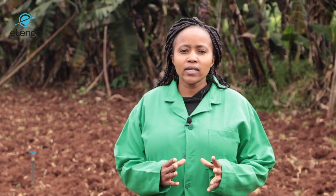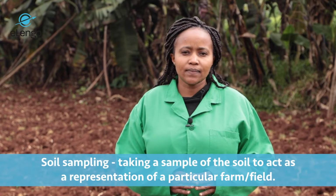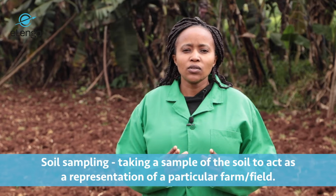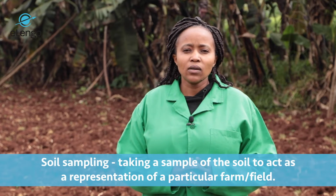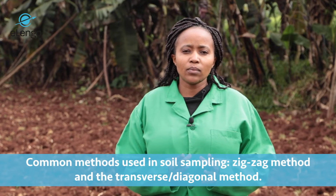In this section, we are going to talk about soil testing and specifically soil sampling. What is soil sampling? Soil sampling is taking a sample of the soil to act as a representative of the soil in a particular field. There are two common methods used in soil sampling. One is the zigzag method and the other one is the transverse or the diagonal method.